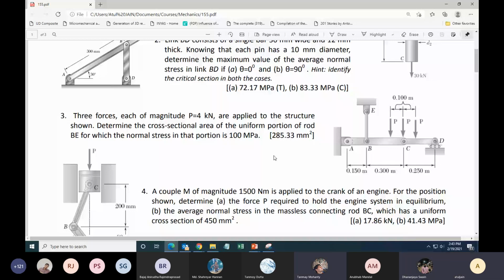Sir, after equilibrium, it would become P by 2, P by 2 on both sides. No. Normally, the third P, you can put it anywhere by using equations of equilibrium. It should balance each other. Irrespective of whether you put it in member AC, CD, or the pin, if you write the equations of equilibrium correctly, it should take care of itself. Our choice should normally be irrelevant.